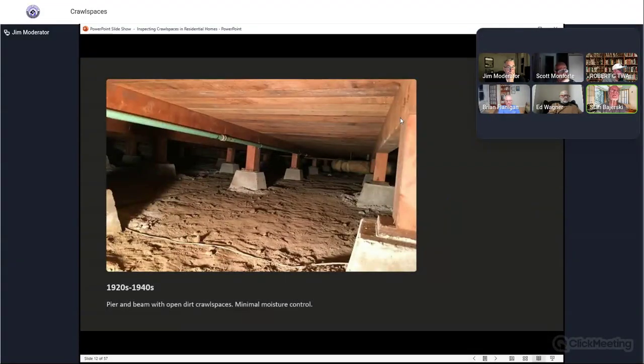Okay, Jim. So here's, maybe not with those footings, but this is kind of typical of what we see around here. You have your posts on; those are nice bases. Sometimes we just see stones or plops of concrete on the grading, sagging all over the place. If you're on a dirt floor, it looks pretty dry there. Just because there's no vapor barrier doesn't mean that there isn't a moisture problem, but that looks fairly dry. And it looks like you could probably get through that crawl space fairly well.